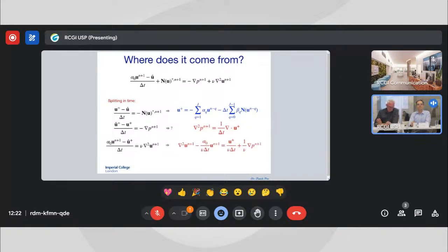And the last part of the splitting scheme, well, I can just rearrange the equation. If you accept I can time march the blue stuff to get the nonlinear terms, if I could solve for the pressure in the second term, then finally I know my u plus hat term, and this is just a Helmholtz problem. That's a linear discretization, the Helmholtz problem. So if I rearrange this, here's my u at n plus 1 times the Laplacian.